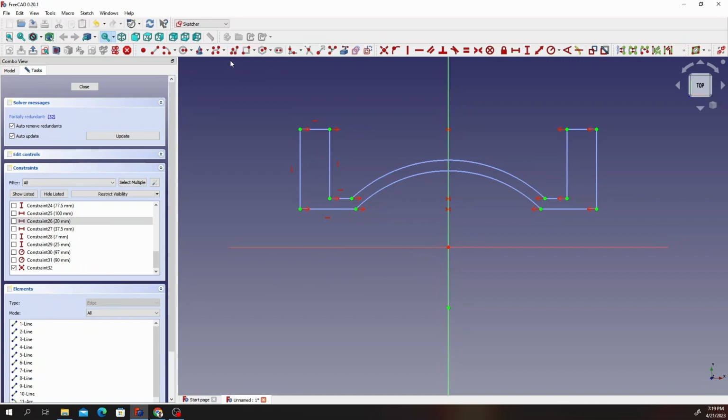Okay. So once we do that, we are going to create another sketch. Just follow along. Let's get the polyline tool. So we shall click somewhere there, draw a straight line, go down, straight line again, go across, make sure it's a straight line, go up, make sure it's a straight line, and then come back here and make sure it's a straight line, and then end.